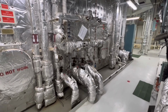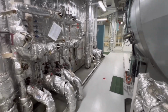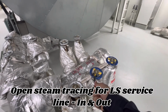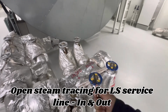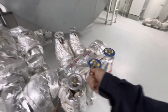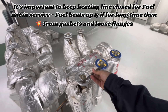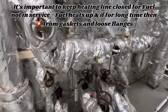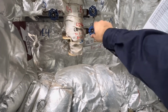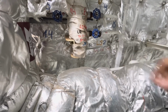So guys, let's begin the changeover for the auxiliary engine. First of all, we have to open the steam tracing. This is the steam tracing for the outlet. First we will open the outlet, then inlet. Outlet is open. Now we will open inlet. Inlet is also open now.